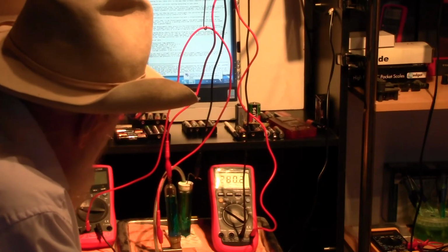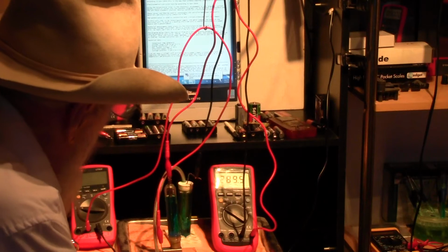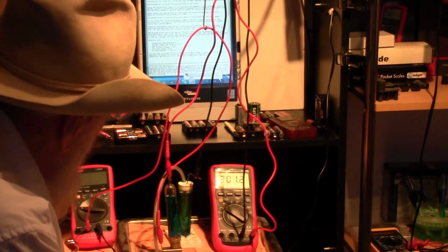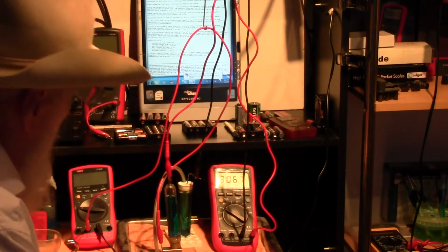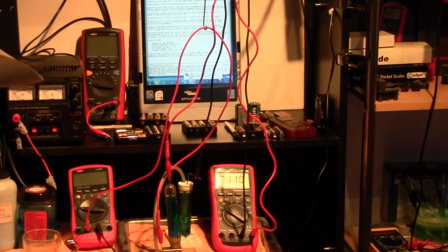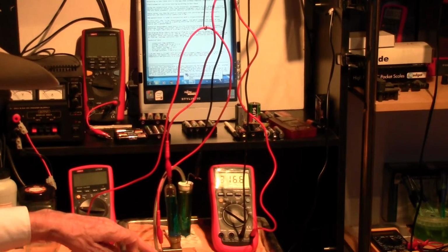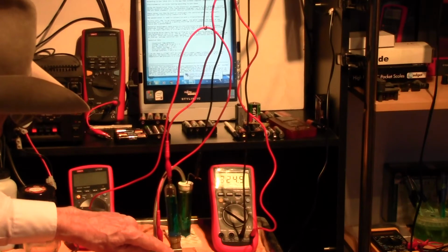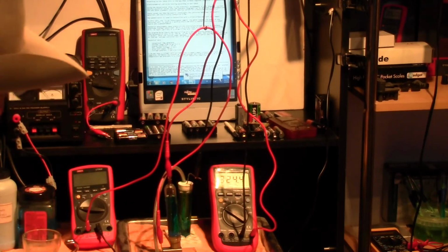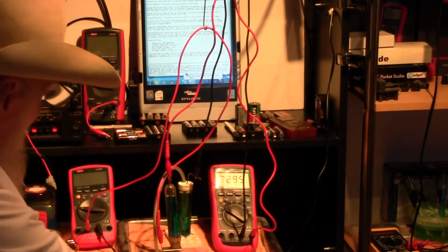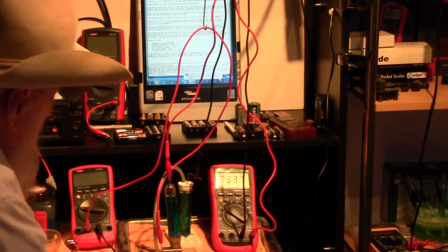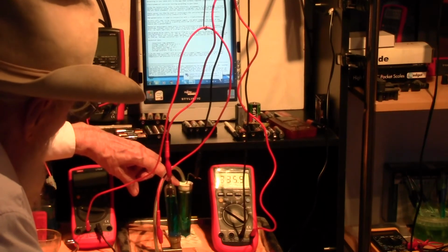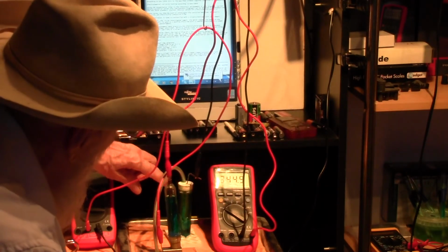Right, it is varying, but we get 280, 290 millivolts, and it is varying. And that variation is because we have a corrosion reaction going on at this point. And what you see on the meter is this corrosion reaction by comparison to the known corrosion reaction in the half cell here.